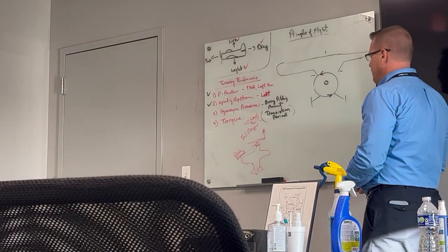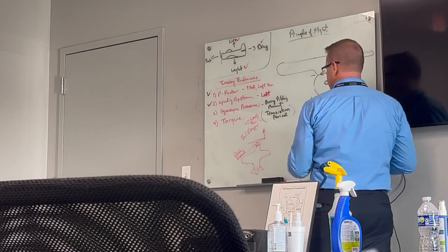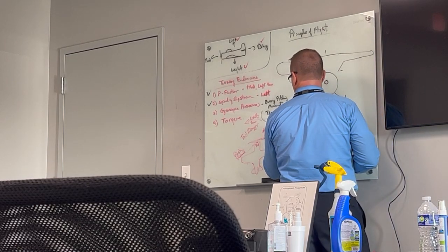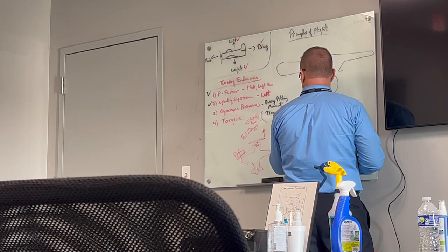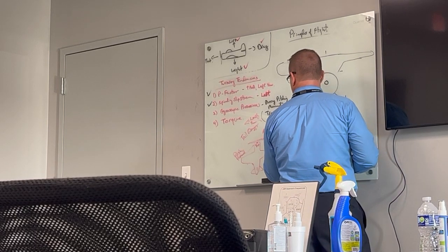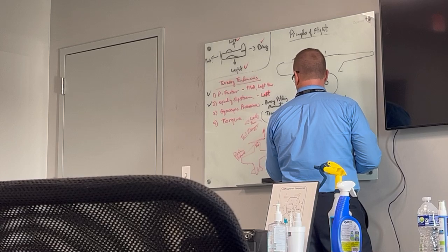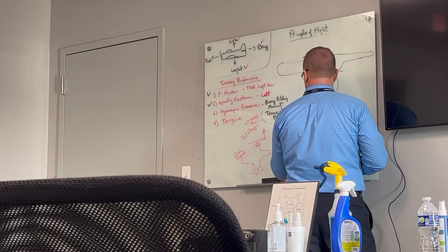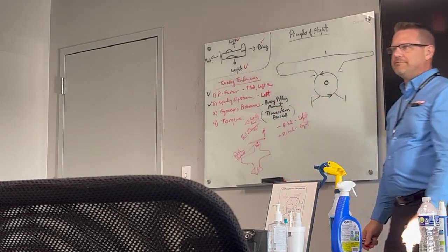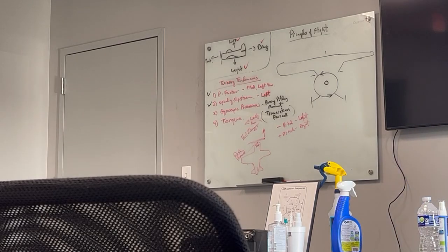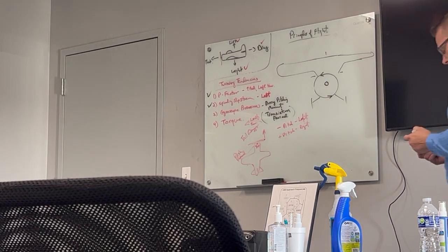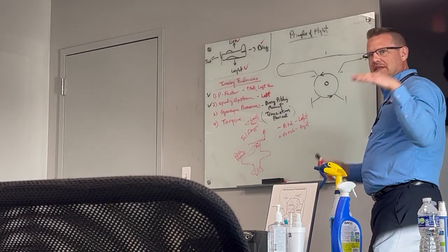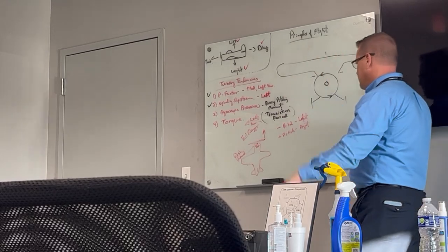So basically what we need to know about gyroscopic precession is if it's a negative pitching moment, it's gonna be a left tendency. It's gonna be a force to the left. And if it's a positive pitching moment or pitch up moment, it's gonna move us to the right. That's the end game of what you wanna get out of gyroscopic precession. But it's only felt during the transitionary period. That's the other thing too. It's only momentary. As soon as you get that established, now it's gone.